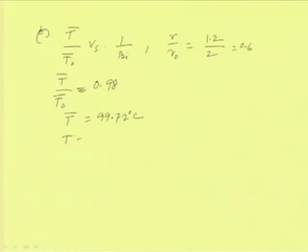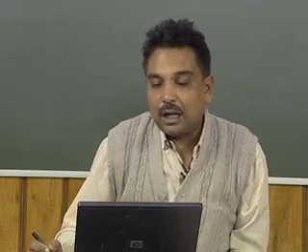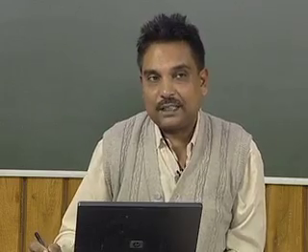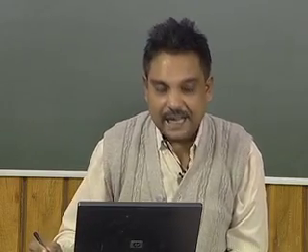From there we can write T is equal to 129.72 degree centigrade. We are finding the difference is about 2 degrees, and as already discussed, this difference of 2 degrees is basically due to the high thermal conductivity of the aluminum cylinder we have considered in the present case.